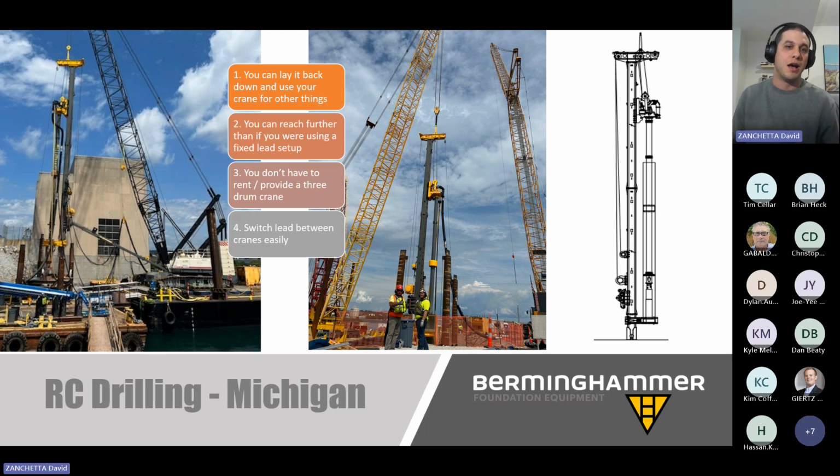Some people might know that this is where Lake Superior heads into Lake Huron, and there's a change in elevation, so there's some locks at that location. And in improving and creating a new lock at that location, my customer was challenged with installing by reverse circulation and case advanced methods some 48-inch pipe piles socketed into rock in case advanced.